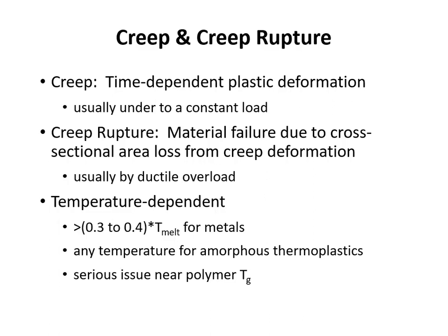So we described in the strengthening mechanisms portion of our discussions how one way to annihilate dislocations was to give them enough thermal energy to effectively diffuse upward in parallel with their own plane so that they had more mobility and could self-annihilate, could come into correspondence with an oppositely oriented dislocation.